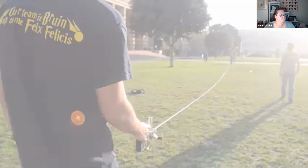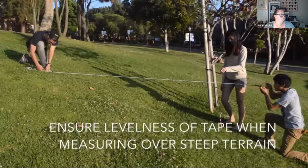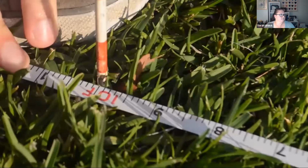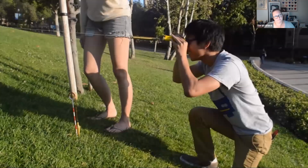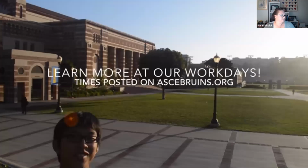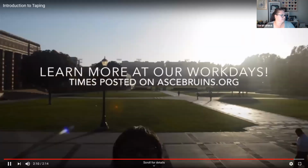If the area you're measuring has a considerable slope, position one end of the steel tape at the highest point and use a hand level and plumb bob at the other end to ensure that the tape is level. Thanks for watching. To learn more about taping and other surveying techniques, come to UCLA Surveying Workdays.